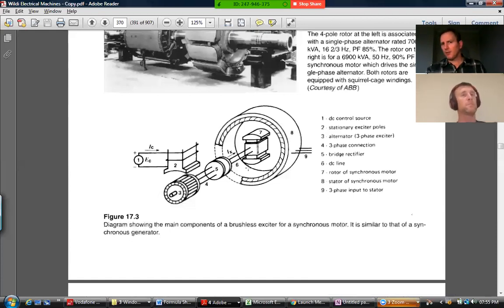So there's a little bit of power wasted in here, but the amount of current that this thing carries, and perhaps even the voltage that's feeding it, compared to the voltage that you might have here on the stator and the stator currents, is maybe 100 to 1 or something. So you're only stealing a small fraction of the shaft power to keep this excitation going.